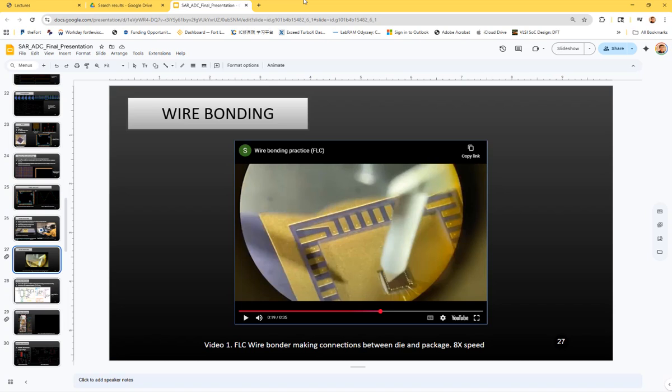What that is doing is giving pressure and also passing ultrasonic vibrations through that wire. But I don't think that really helps the solder connection. I think the ultrasonic signal just gives a little vibration so the wire can go through the tip smoothly. It's not getting stuck in the capillary space inside. But what really makes the connection is just the pressure. Very interesting, right? Okay.